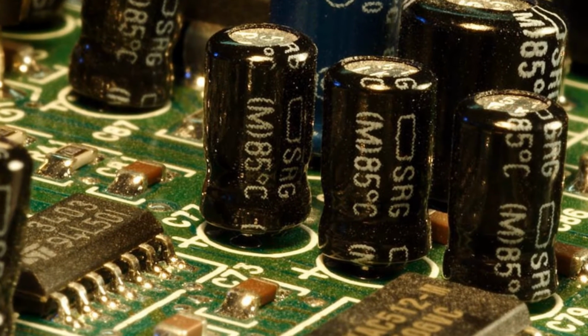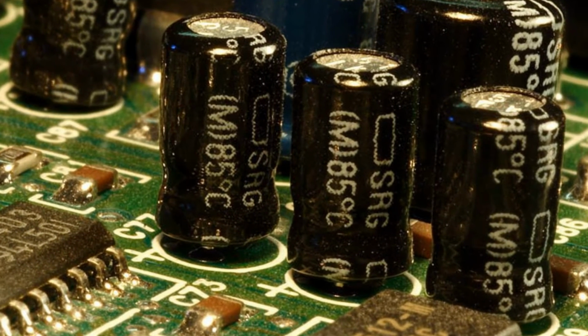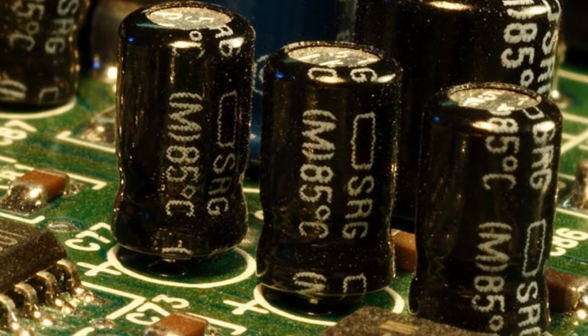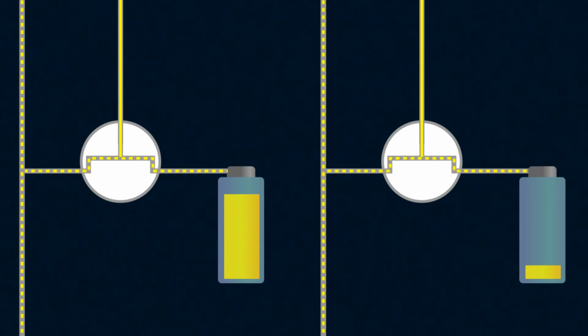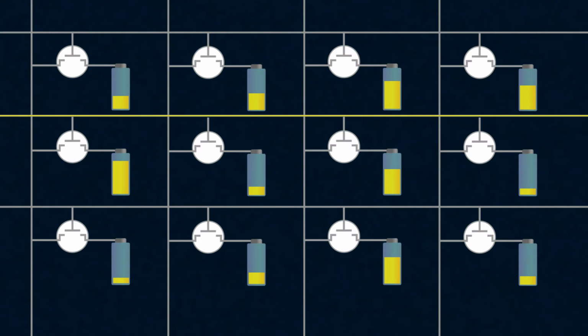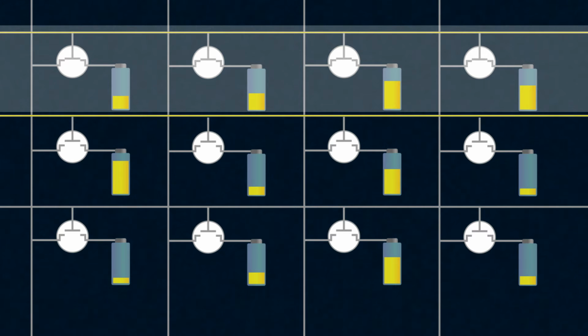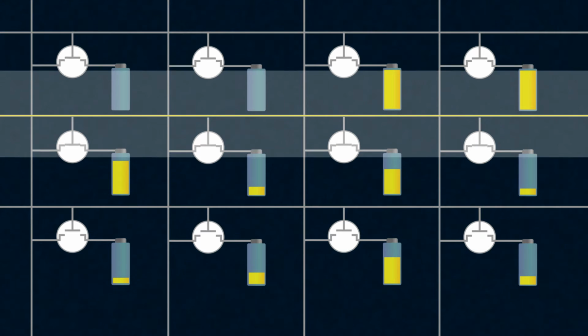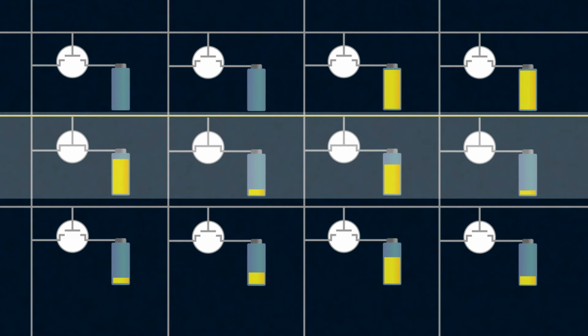However, capacitors have one problem. They tend to lose charge over time due to various reasons. Moreover, in our device, this process is exacerbated because during each read cycle, we drain a bit of charge from each charged capacitor and inject a bit of charge into each discharged capacitor. Therefore, for capacitor-based memory, a refresh procedure is also necessary, during which slightly discharged capacitors need to be recharged to the maximum, and slightly charged ones, contrary to our intention, need to be completely discharged.